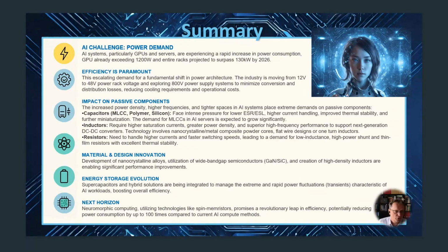Impact on passive components: in general, all components need to work at a higher frequency, with lower parasitics and an increased frequency range, and be capable of working reliably, long-term, continuously under higher thermal load. It calls for development of new materials like nanocrystalline alloys for inductors, or new dielectric materials for ceramic capacitors, to answer the need for wide gap semiconductors and the trend in GPU coupling.